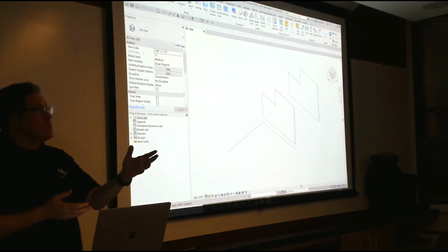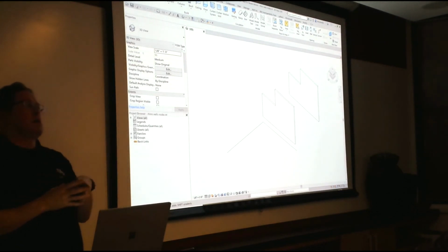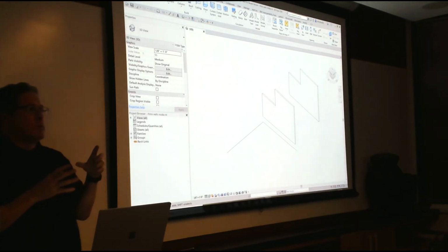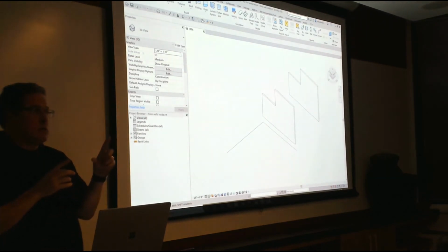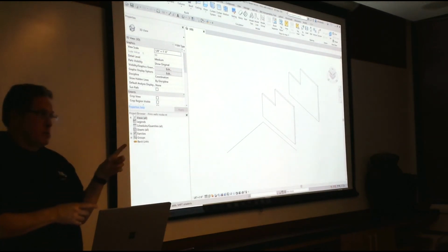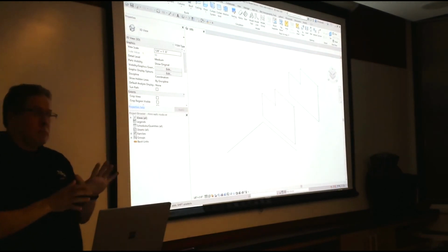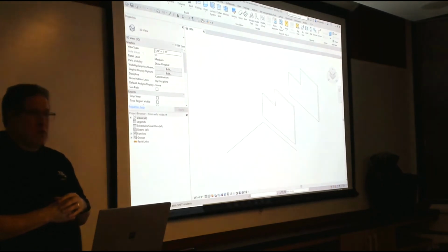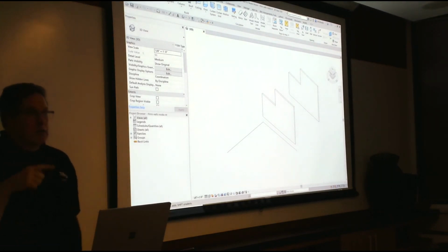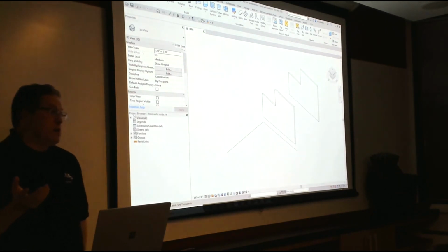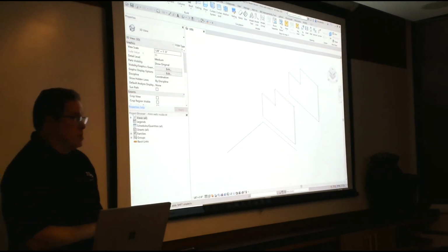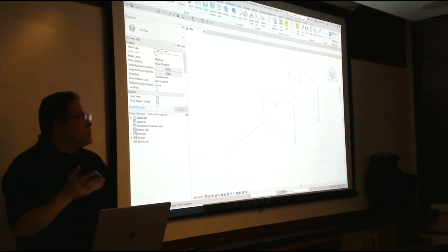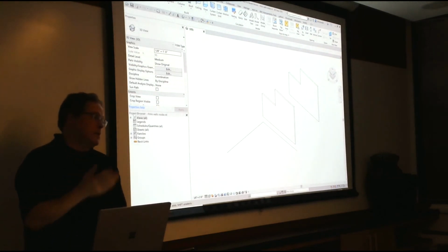And so a more accurate way of saying this is, relative to Revit, it's faster to have Rhino around. Right. Okay? Now, that doesn't mean that there aren't workflows that are going to take half an hour. If you had an adaptive component and Grasshopper's placing 10,000 adaptive components that are complicated, it could take half an hour, right? It's not Grasshopper's issue, it's just that the adaptive components are being calculated by Revit, that's how long we wait.